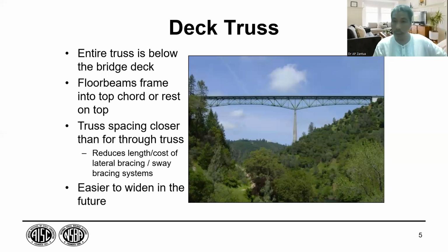Deck truss type of bridge. So the substructure? Actually, this is still a superstructure, because it is directly supporting the pavement. The bearing is located here, so this is above the bearing. So the truss is still on the superstructure.